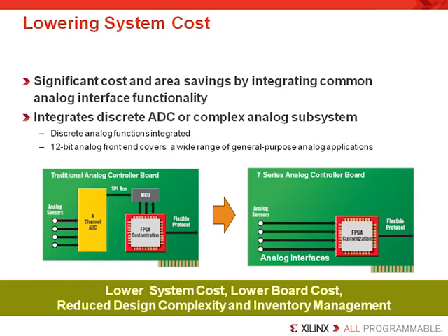A single chip solution can be realized when you use a Xilinx FPGA with the programmable XADC integrated and implementing a soft microprocessor. This brings down the cost and complexity of the overall system, especially if you're talking about an RTX device or FPGAs around the $10 price frame for the applications that we're targeting. In this case, it would add an awful lot of value. Now, the single device solution not only simplifies the bill of materials and reduces cost, but also provides improvements in board area, pin savings, FIT improvement, and better inventory management.